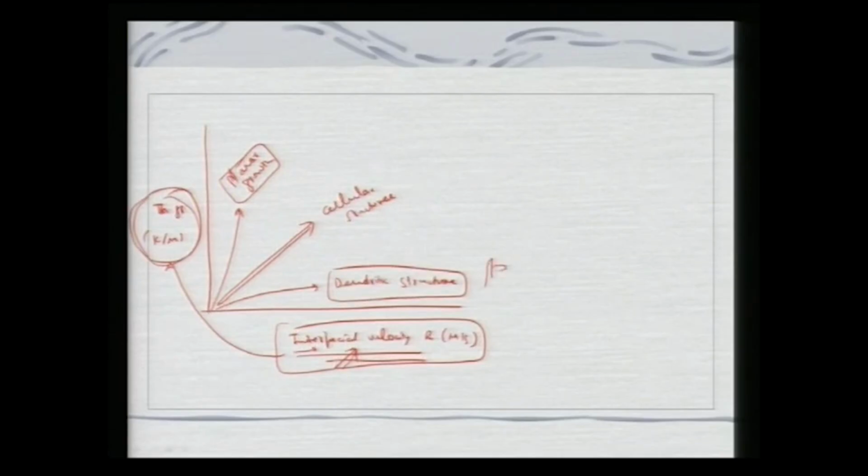So, what am I getting? The entire material is getting transformed or solidified, so I am getting a much coarser, planar growth of the material. If I keep my interfacial velocity very high, while not providing enough thermal energy, that is, the thermal gradient is not enough, then what I get is a dendritic structure, with secondary arms, primary arms and so on. In the planar case, I get a very coarse microstructure because the entire interface basically starts growing in a similar fashion, but in the cellular case I get a very refined microstructure.